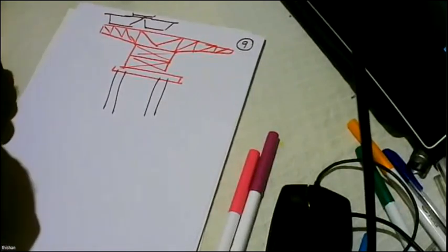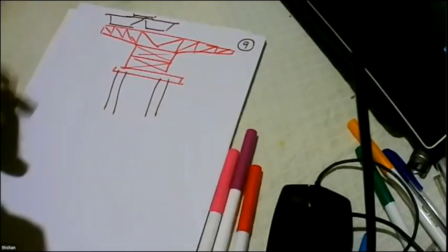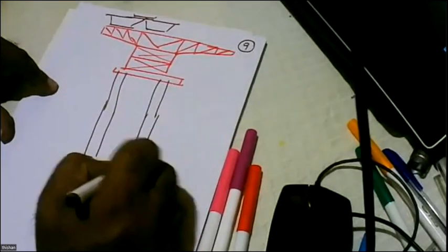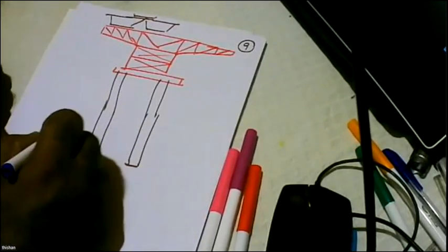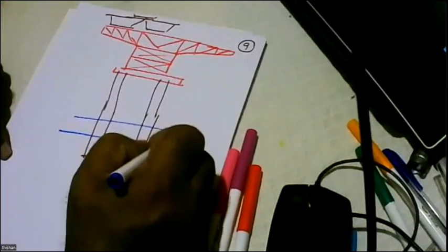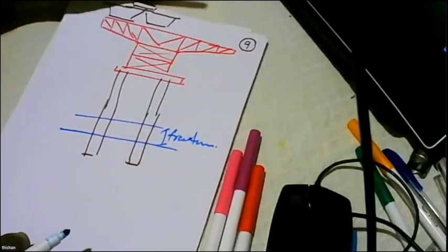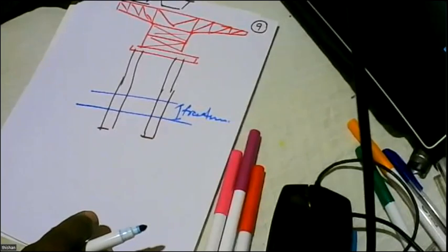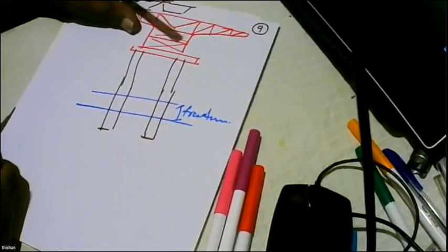So how the foundation is going to respond? But when it comes to the vertical load carrying capacity, you are pretty sure that you know, because you have done some reasonable socketing, and then there's some fractured rock as well. That also can give good skin friction. So you are pretty sure about the piles. But what is not sure is how these piles are going to behave when they are subjected to bending.